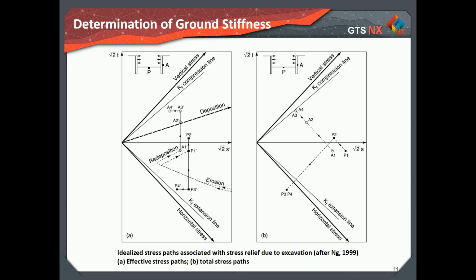As the mechanical behavior of soils depends on the current effective stress state and stress history, it may be important to obtain soil stiffness estimates from tests which follow a stress path compatible with that experienced by the soil at the particular site. And discuss this problem, and his approach is shown in this figure.